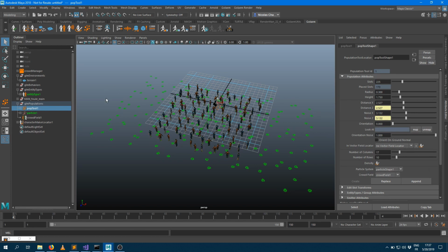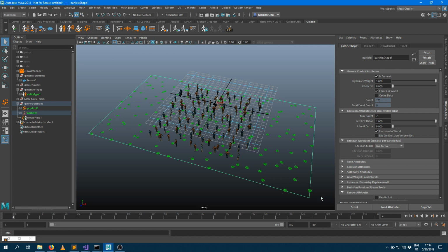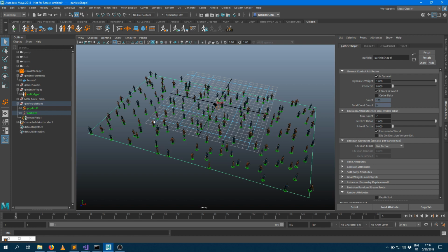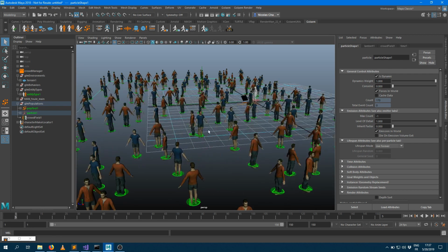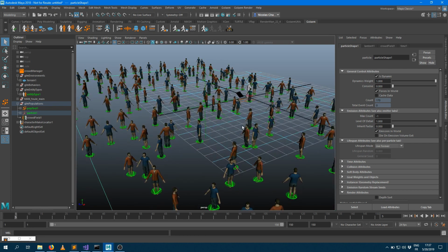And if you want this to be applied, you need to press the replace button to replace the previous node you've created. So if you press replace here, now it's been replaced. And once again, if you want to see the result of that, you need to go back to the first frame and play a couple of frames and see what's going on. Okay, now we're quite good.